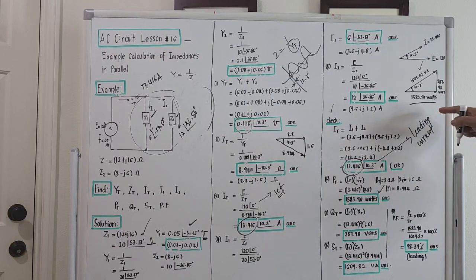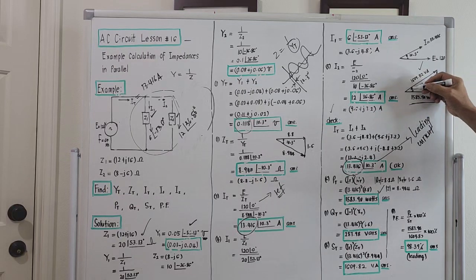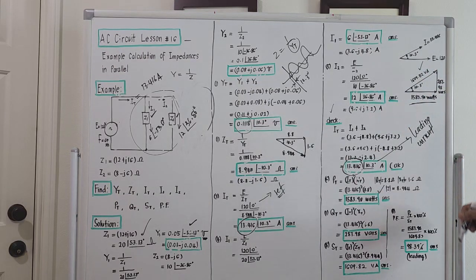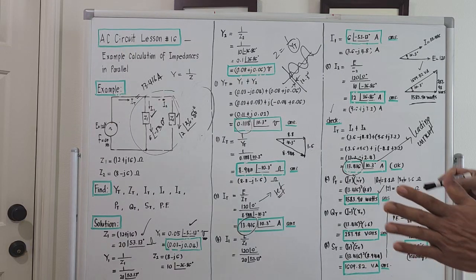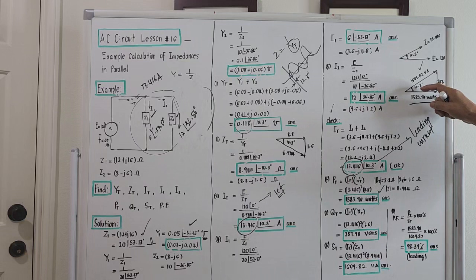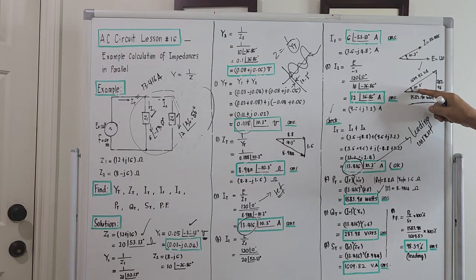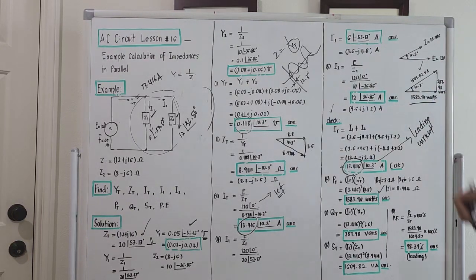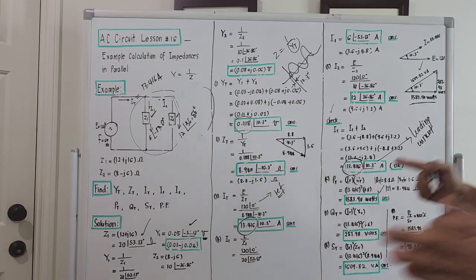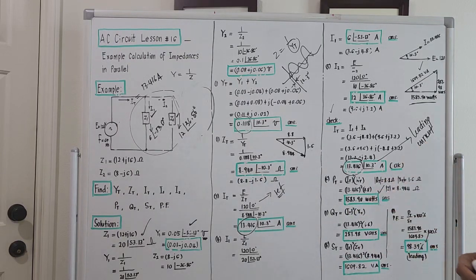Okay, and for the power factor, by definition, power factor is the ratio of true power over the apparent power. It will be 1583.90 divided by 1609.82 times 100%. It is 98.39%. Or another solution for the power factor, take the cosine of this angle here. Cosine of 10.3 is 0.9839 times 100%. So it is still 98.39% as it checked to the value of the power factor.